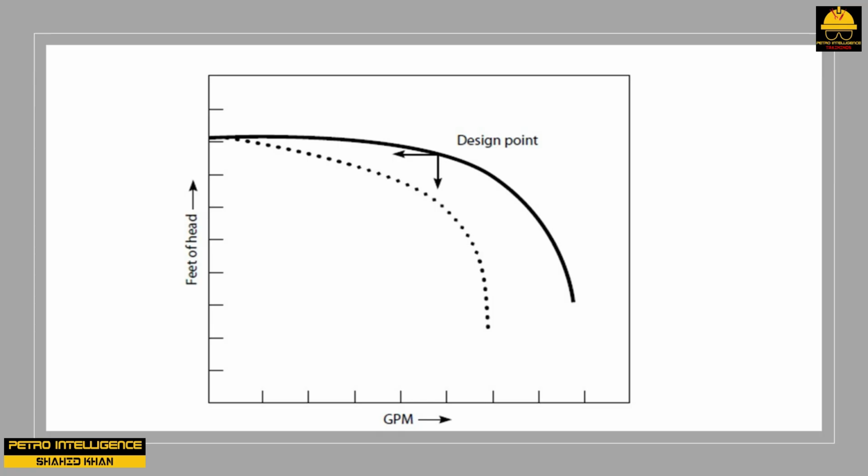That is, a reduction in pump suction pressure of 1 psi causes a fall in pump discharge pressure of 100 psi. Raising the level in the vessel from which the pump is taking flow by just 2 feet dramatically increases the pump's discharge pressure. It seems as if the pump's performance jumps from an inferior performance curve to its normal performance curve as shown in picture.